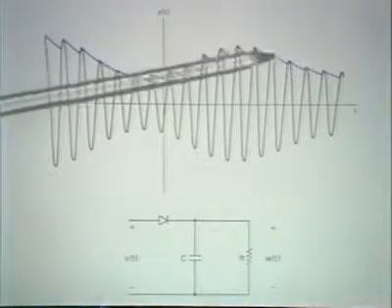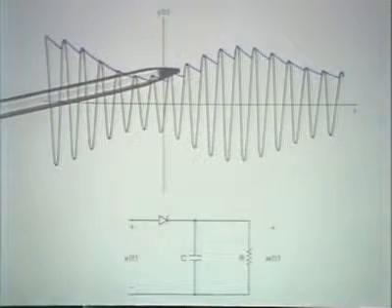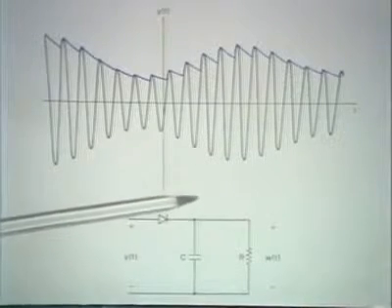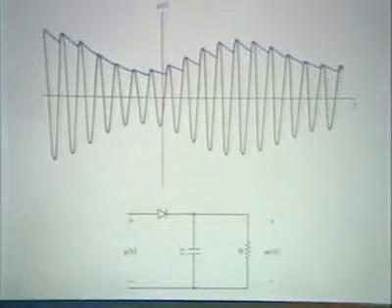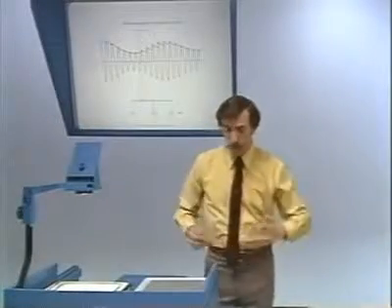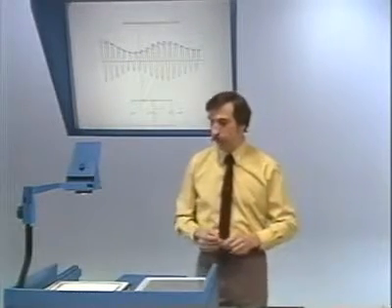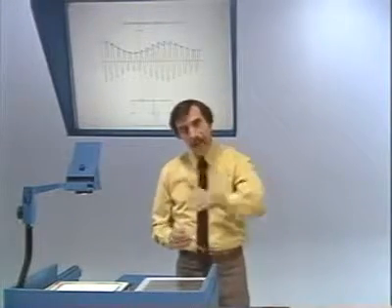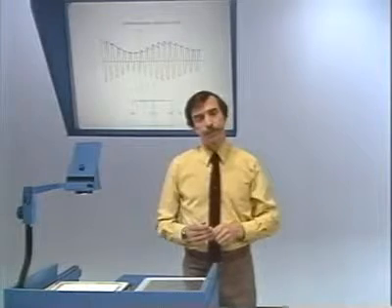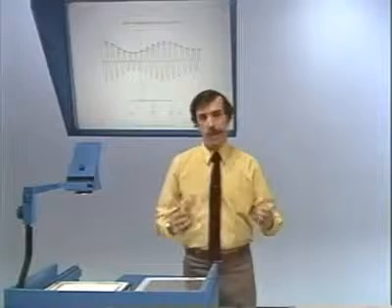It's a demodulation that doesn't require synchronization between the modulator and demodulator, and it's fairly inexpensive to build, but it has obviously some trade-offs associated with it. To indicate where the trade-off comes from, or where the issue surfaces, notice that what we're doing is tracking the envelope of this sinusoidal signal. And we're assuming that that is our original signal x of t.